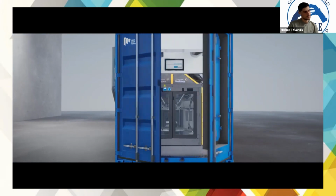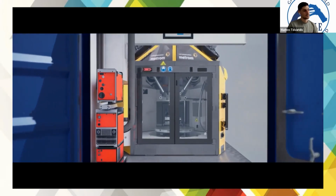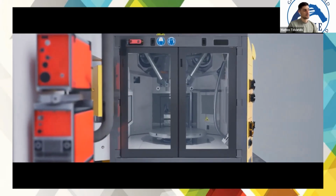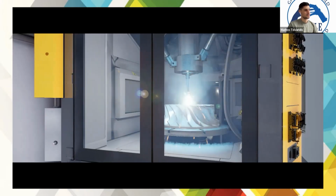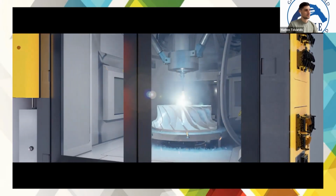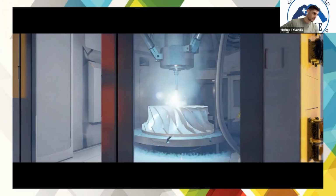After starting the printing job manually, no more supervision is needed. The machine measures the building panel and starts the 3D printing of your component through a layer-by-layer application on the building platform. The built-up part is then finally machined by CNC milling. If needed and compatible, pressing tools are installed to smooth out the surface roughness of the component.